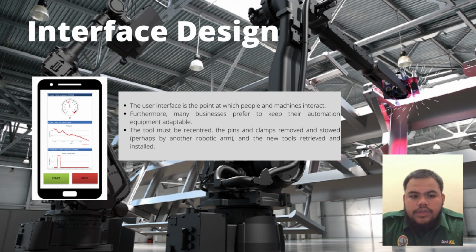When it comes to the fixture changeover, it's helpful to think about it as one component of a bigger system. The design must also prepare for the storage and retrieval of fixtures when they are not in use to achieve maximum efficiency in welding automation. And automated fixturing and changeover may be programmed to read the barcode on the component, shift the correct fixture into place, check the correct pieces are being welded, and finish the weld.